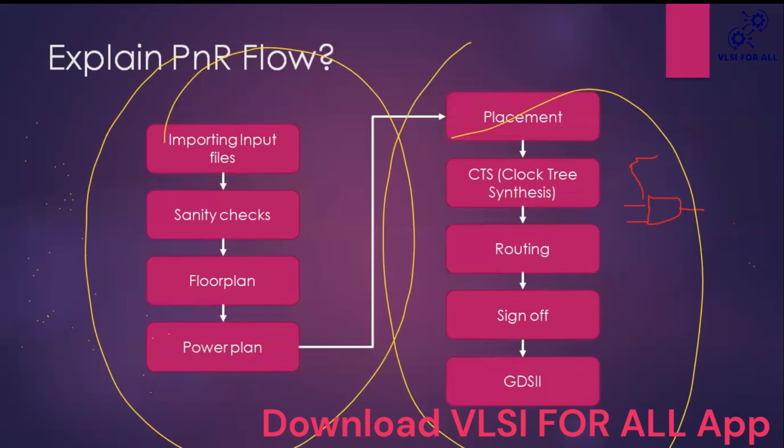During legalization, it tries to avoid all the placement DRCs: if standard cells are overlapping, it will move them aside and align them to the rows. All this happens during legalization.